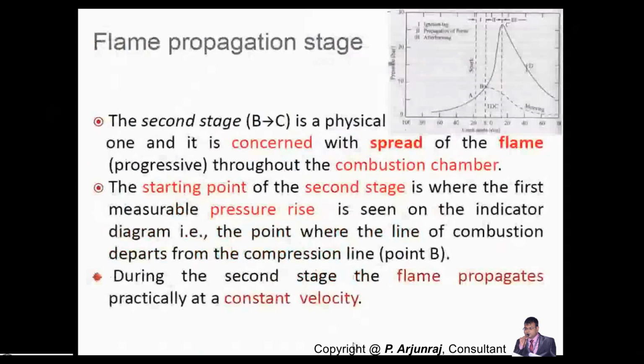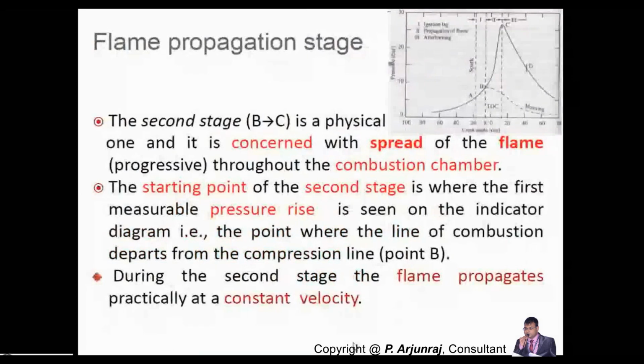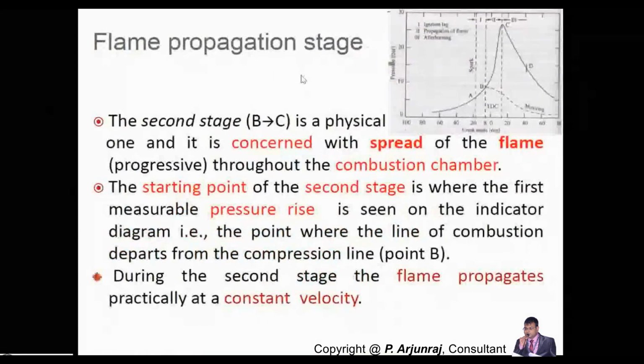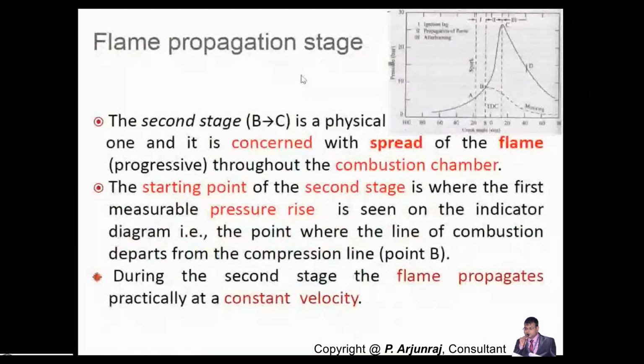The next important stage is the second one, where you get the real pressure rise, from B to C. It is nothing but the flame propagation stage, where you increase the velocity of the flame. Again, it goes from higher width to the narrow width.